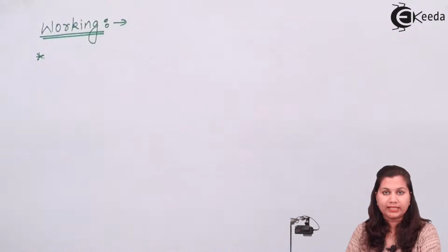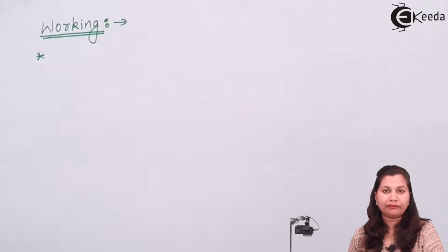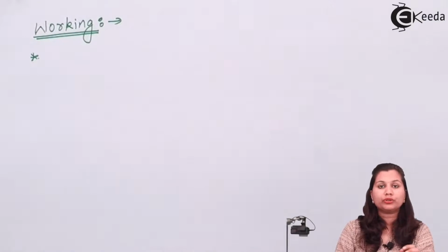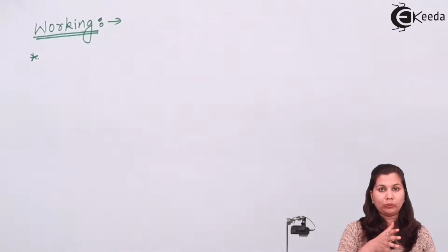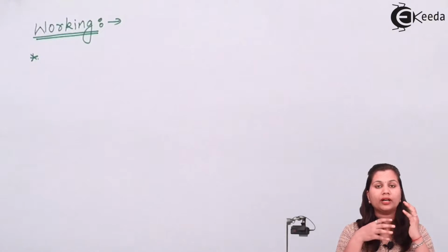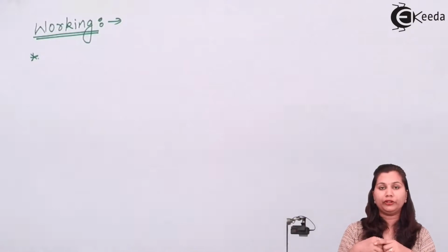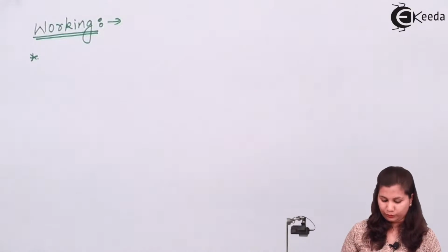Due to this alternating current flowing through the primary winding, or the excitation of the primary winding, an electromagnetic field is produced. This induced electromagnetic field is going to induce alternating currents in the two secondary windings, S1 and S2.